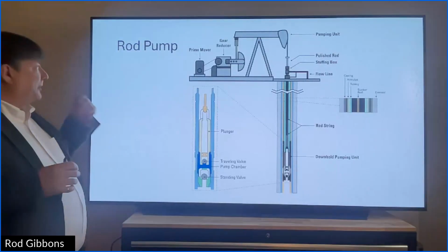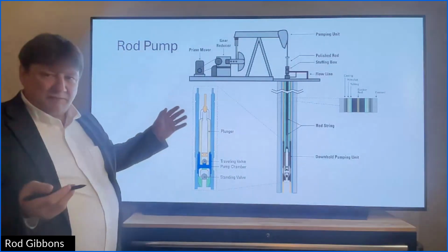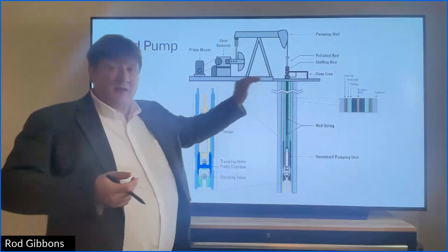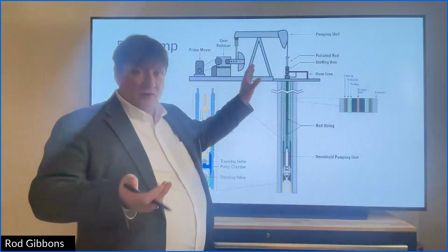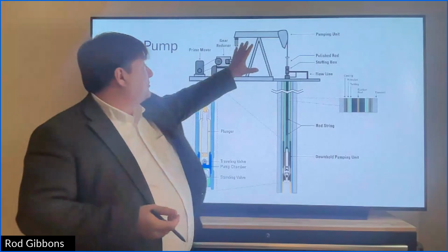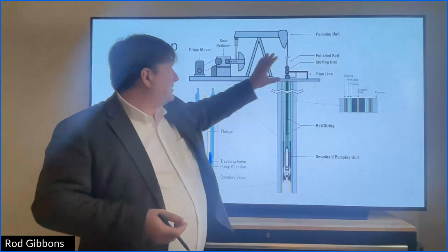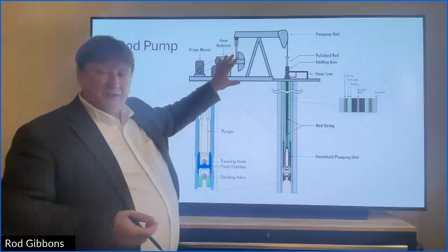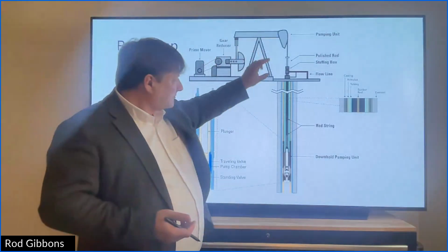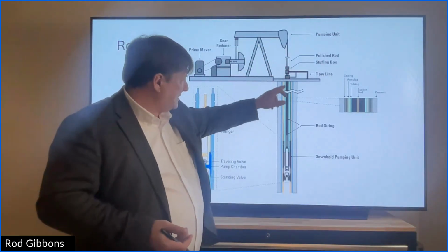So what's a rod pump? Well, this whole system you could refer to as a rod pump. You may see these at surface, driving around Alberta or Texas, on land, or for sure you've seen them on TV. There's a pump jack or pumping unit. This is the surface equipment. This is what puts the energy into the system, that gives us a bit more, overcomes that potential energy. And then it's connected through the wellhead, Christmas tree, down.